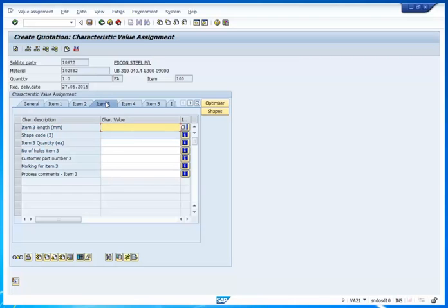If we go to item 3, we basically now need to specify the individual components for item 3. On this particular occasion, let's do a 7.2 meter length. We'll leave that as a square cut. We need 1 of those, and we'll put some marking instructions there again, A, B, C, and we'll do -3 for this particular component. So we've finished our 3 components.